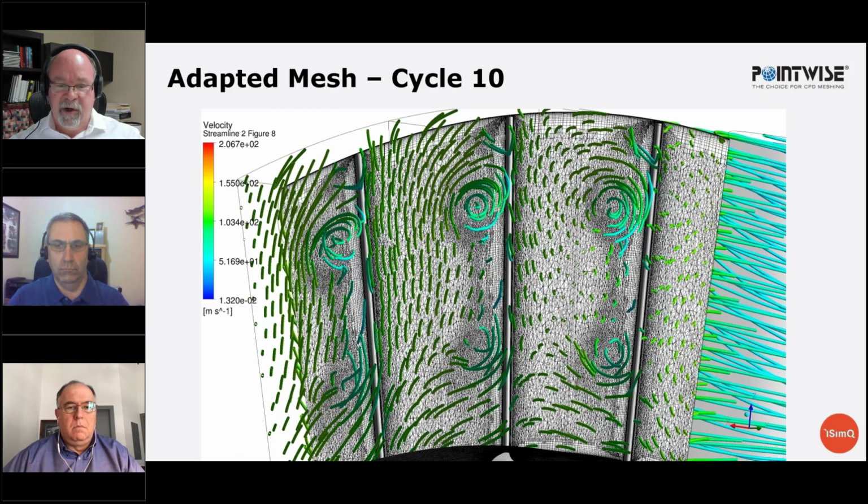And if you plot the mesh here 3 times just for clarity, you can see the mesh. First of all, it's been really sensitive to the tip leakage flow. It's resolved the tip flow as it spills over the top of the blade, and the mesh has actually picked up these secondary flow features of the vortex coming out to the trailing edge. So very subtle flow feature, picked up very nicely.